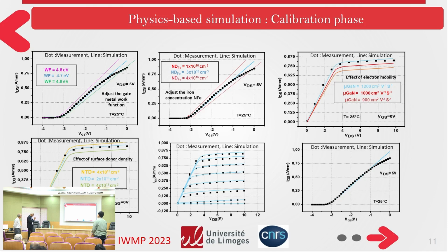Why do I say this? Because for class AB power amplifier operation I always put the bias near -2 or -1 volt, so I never go up to 0 volt. At 0 volt the channel is open, so, sure, we can look at surface traps and buffer traps by looking at GM. I made a lot of measurements, but I never observed this.